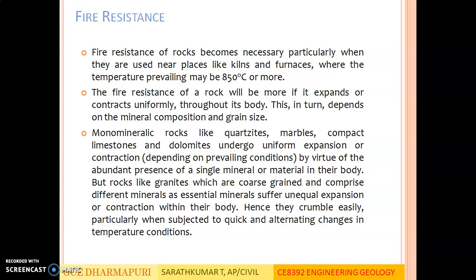The fire resistance of a rock will be more if it expands or contracts uniformly throughout its body. Mainly it depends upon two criteria: mineral composition and grain size. Monomineralic rocks like quartzites, marbles, compact limestones and dolomites undergo uniform expansion or contraction by virtue of the abundant presence of a single mineral or material in their body. So their mineral composition should be made up of